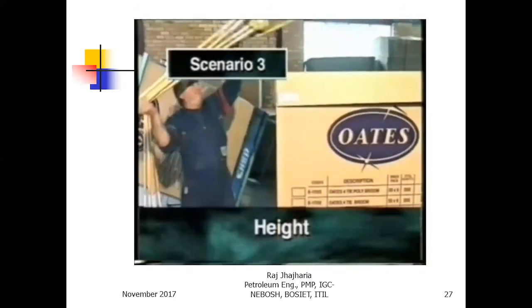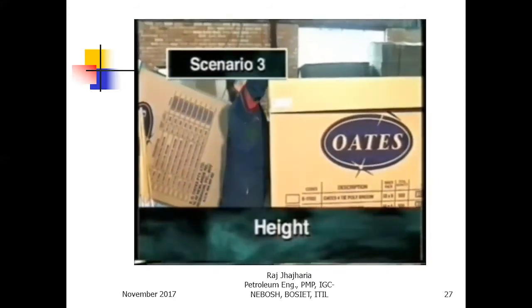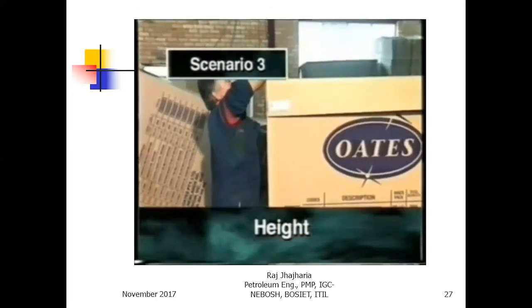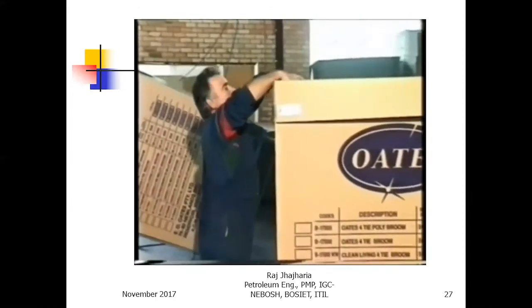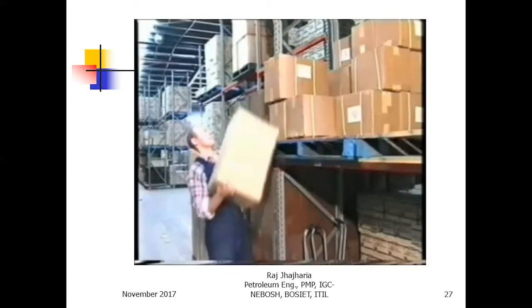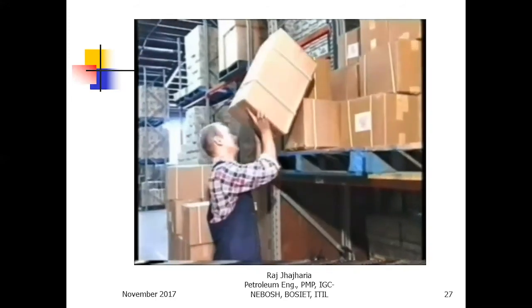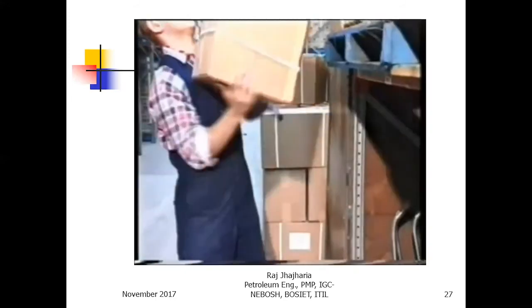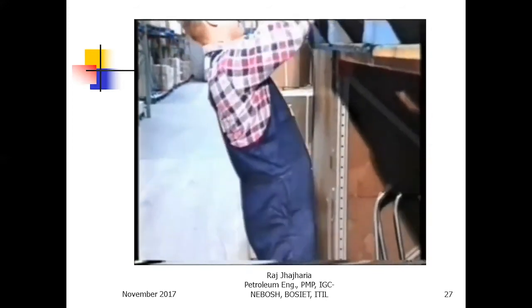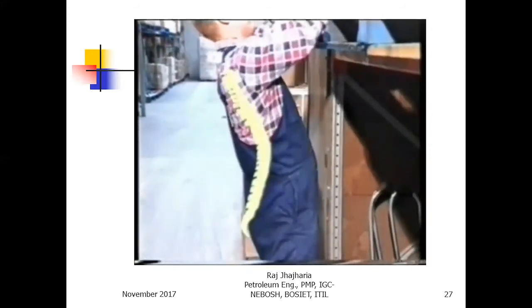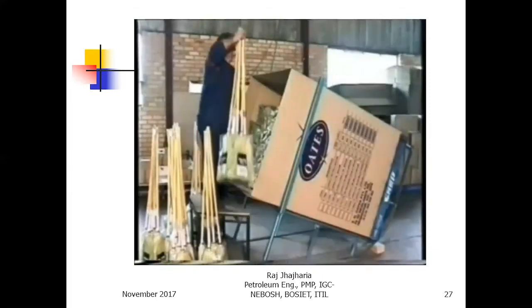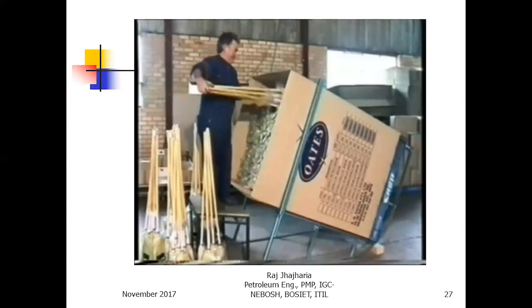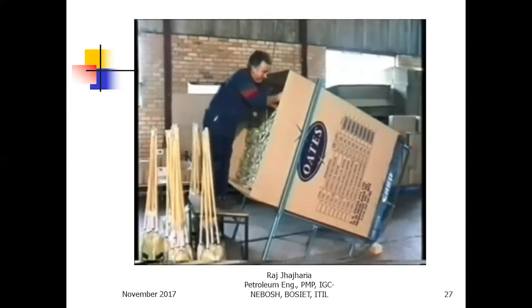The employees in these scenarios are creating extra pressure on their necks, shoulders, and lower backs by having to repetitively lift objects above a comfortable work height. You can see how this person's neck is extended back and how his lumbar region is excessively arched due to the extra weight caused by lifting this load above his head. A work platform and adjustment to the loading system has helped to reduce the risk for this employee.